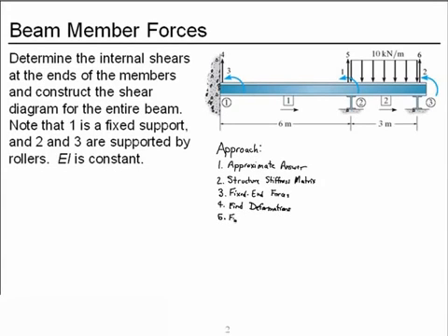Then we'll find member forces, specifically the shears at the ends of the members. We use that to construct the shear diagram.